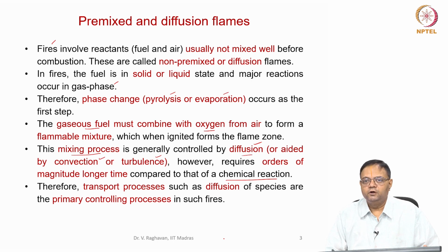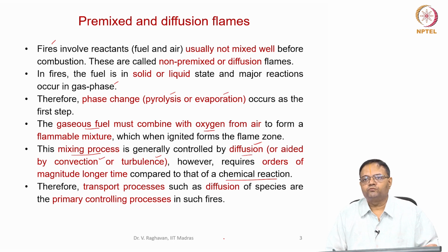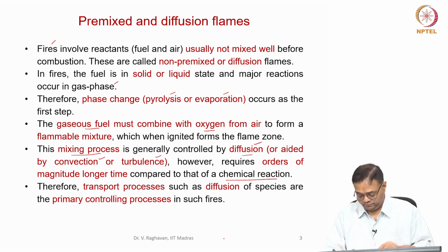The heat flux from the flame to the surface, which is a fraction of the overall heat release, is also important to sustain this. So, the multiple steps involved are the creation of the gaseous fuels, which is due to pyrolysis or evaporation, then the mixing of the gaseous fuel with the oxygen from the air, then the heat feedback to the surface.